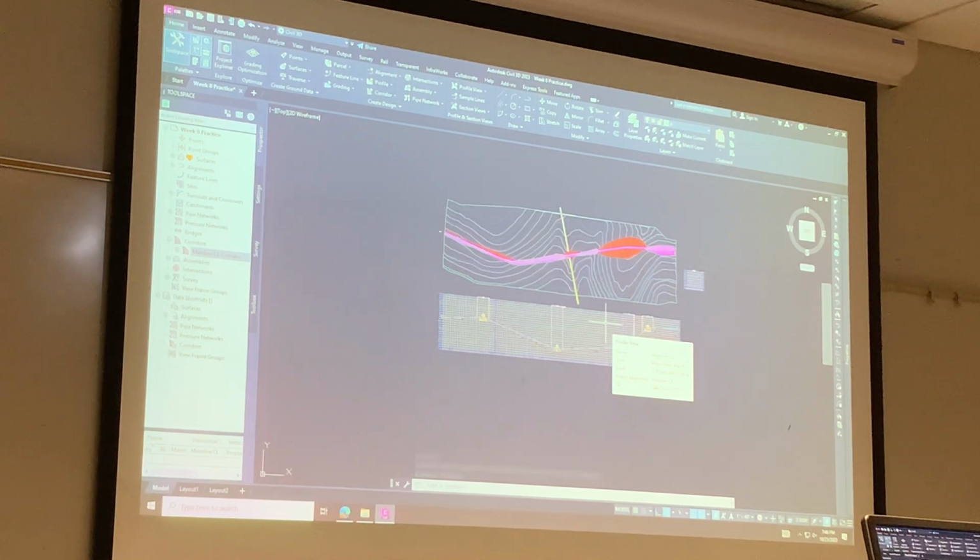When I made my corridor, I didn't just put fill and cut lines, areas. Okay, so that means either that you didn't, so I guess it could mean a couple things. One, did you use the right profile when you were creating the corridor?